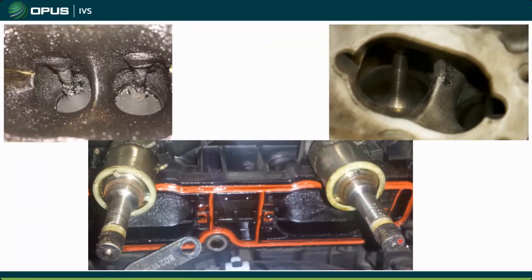And if they look like this, you may want to replace these, because I will tell you the holes on these injectors are very, very small. And it does not take much to, not really so much clog them up, although that does happen. But really what you're worried about is your spray pattern. If it affects your spray pattern, that can affect the atomization, and can lead to all kinds of lean mixture faults, rich mixture faults, rich misfires. You could get cylinder wash down. It could go downhill pretty quickly.